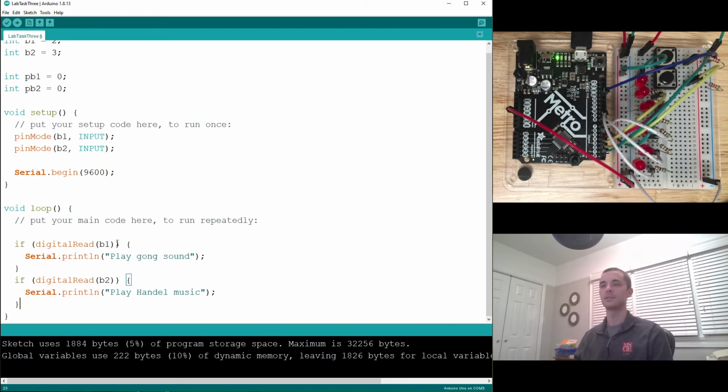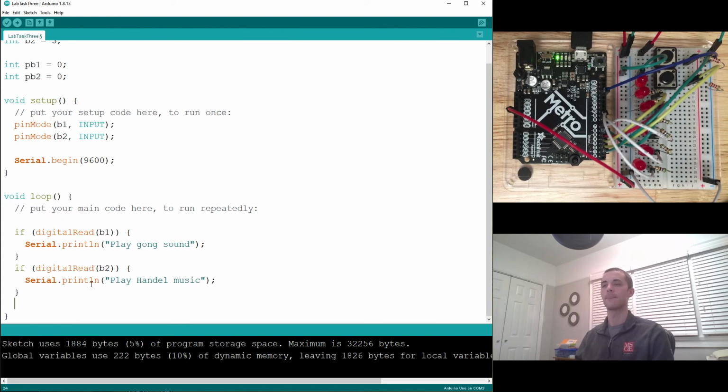And down here, at the very end, we can say previous button 1 is equal to, this is again imperfect in how we're setting it up, because in theory I could release the button in between these two being read, but this will be accurate enough for what we're attempting to do.